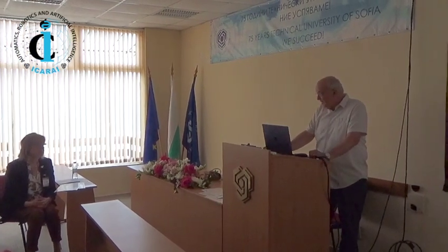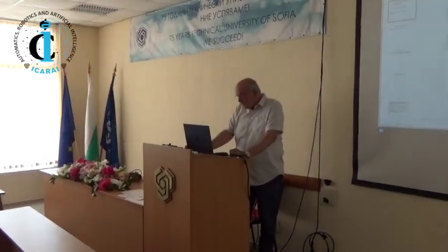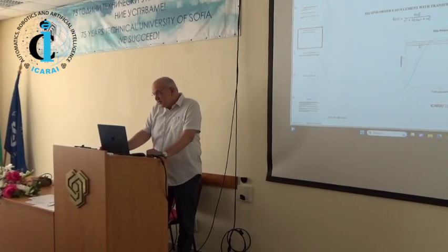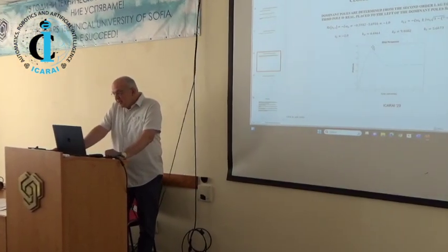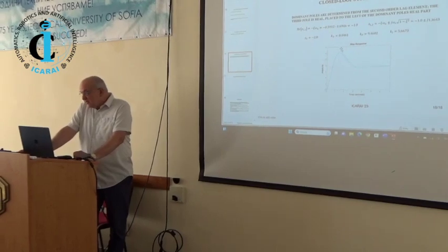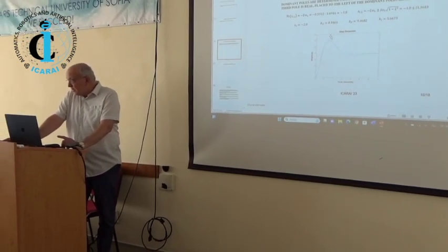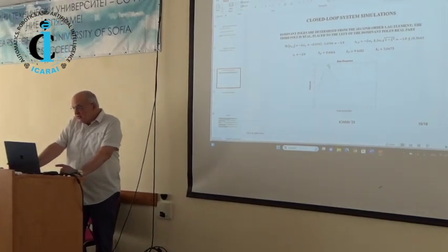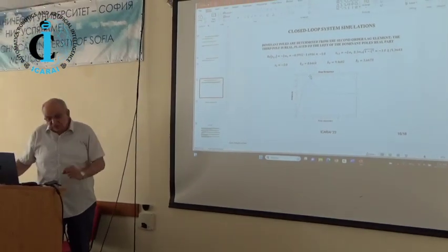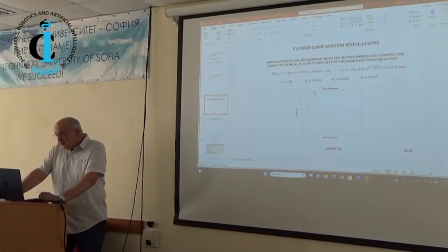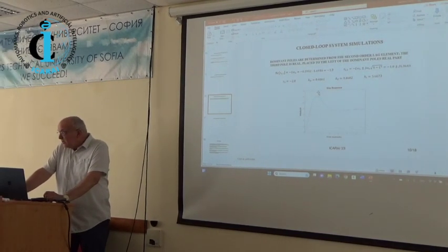40% overshoot. It's a tricky system, and my initial setting was less than 10%. So basically, one of the research goals here is to show the dependence on the placement of the third pole, which is not dominant. The dominant are these two, which are shown there. How the placement of the third pole influences the behavior.